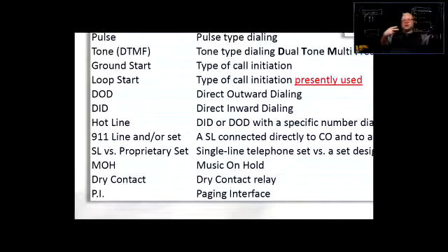So when you install that line and you bypass all the sophisticated telephone system circuitry, you run that line, you cross-connect that in the terminals, and you run that line to the outlet or the telephone jack, and you get the most basic telephone that doesn't require power, nothing. It just needs to be connected to the line. And we are required to do that. Okay, so 911 telephone. So when it comes to installing a telephone system in larger companies, you might ask the client, okay, where would you like your 911 phone? And they will know what you're talking about, right?